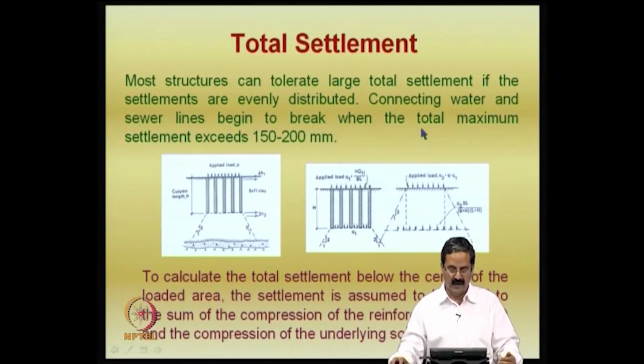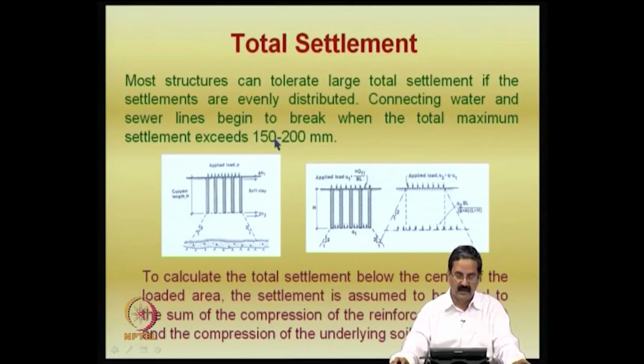That we will see. Why are these settlement calculations required? Say, for example, the water supply lines and sewer lines cannot tolerate differential and total settlements. If the settlements are going to be higher in materials, then they crack and break up. So here you can see a simple diagram in which this is the loaded area. You would like to calculate the settlements.